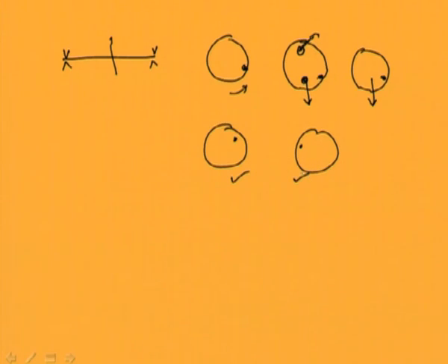That means we have achieved the static balance. But most of the rotors in practice are not in a single plane, and we need to go for the dynamic balancing of such rotors. And when we need to go for dynamic balancing of a rotor, we should have provision for rotation of the shaft, so that the dynamic effects are predominant and we are able to find out their effect.